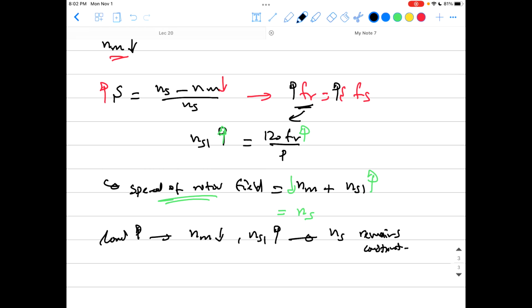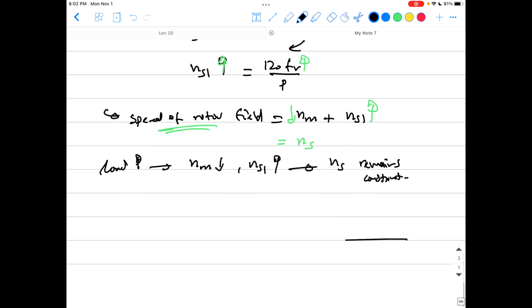constant. Like we said before, the rotor field and the stator field are magnetically coupled together and running at the same speed, which is the synchronous speed all the time, whatever the load is, okay? The load affects the mechanical speed, which is the speed of the rotor, guys. So refer back to the car we're talking about. That is the rotor body, okay? But here is the magnetic field of the rotor running on top of it. So this guy is running by Nm, and this guy runs on top of the car by N slip, yeah?